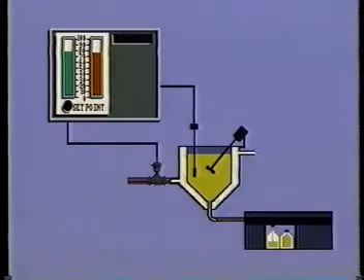The temperature control system was similar to a simple thermostat with an automatic valve that regulated the flow of steam to the jacket surrounding the tank. The controller received a signal from a temperature sensor in the product. A sensor is a device that measures the value in question, in this case, temperature.